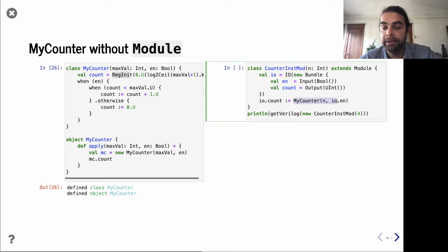And remember, this whole thing returns an instance of the class, but this is actually going to return just that field, that register, and that register happens to be connected to a circuit involving those muxes and the adder and such, and that's going to get passed through, right? So we're creating this snippet of a Chisel graph. I think of it as, okay, here's a register connected to a mux, connected to another mux, connected to an adder. That snippet, we're only pointing to just the register. We're going to pass that over and connect that to the output.